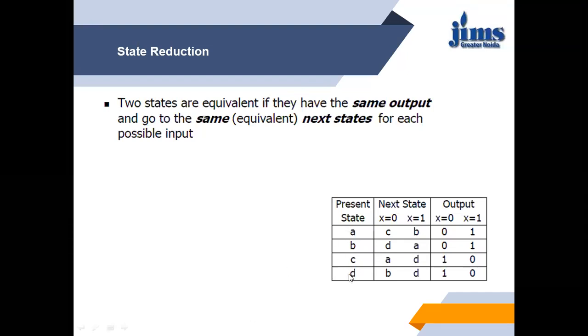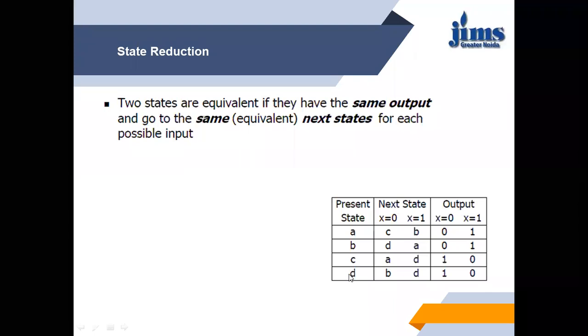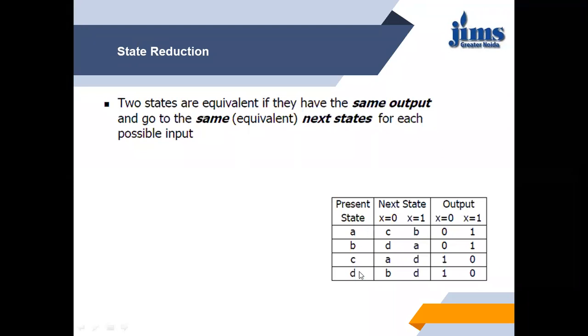There are four possible states, and if we use flip-flops to design this synchronous circuit, we need at least two flip-flops, because of four possible combinations.